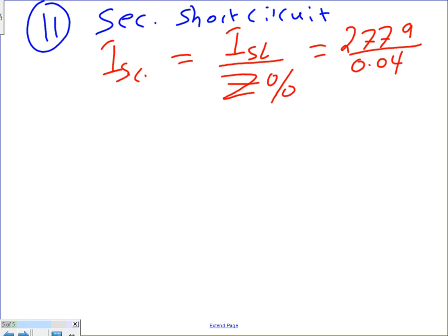Code reference. Not there. Yeah, that's fine. I have to think about it. Okay, if you do the math, I didn't do the math on this one. Can somebody do that, please? Oh, 70 kA. So when Todd and Jerry were here, they said you size your overcurrent protection device to handle 70 or more.